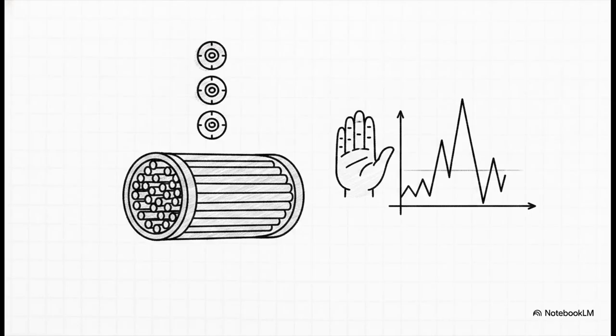Because these 3 lags sit in series right between your control inputs and your temperature measurement, heat exchanger loops are notoriously slow. They are the textbook perfect definition of a high-order S-curve, and they will easily, and I mean aggressively, overshoot if you impatiently tune them like they're some fast flow loop. You absolutely have to wait out that dead phase.